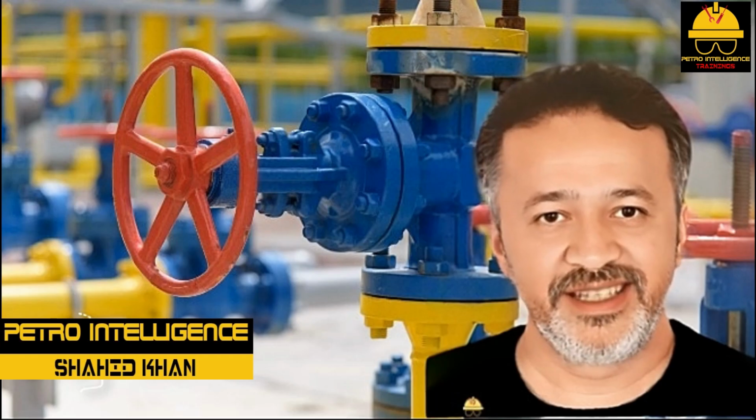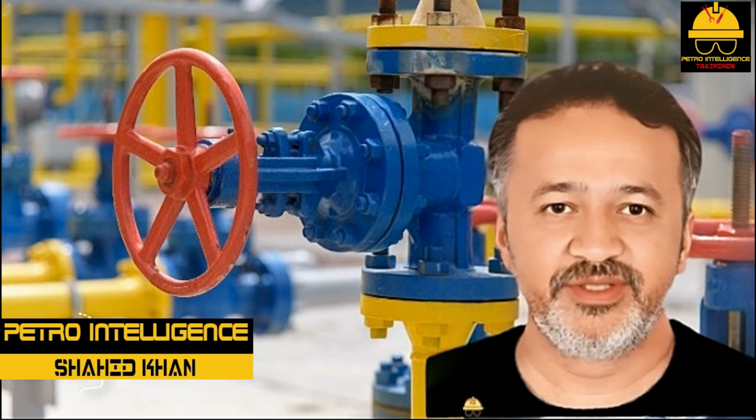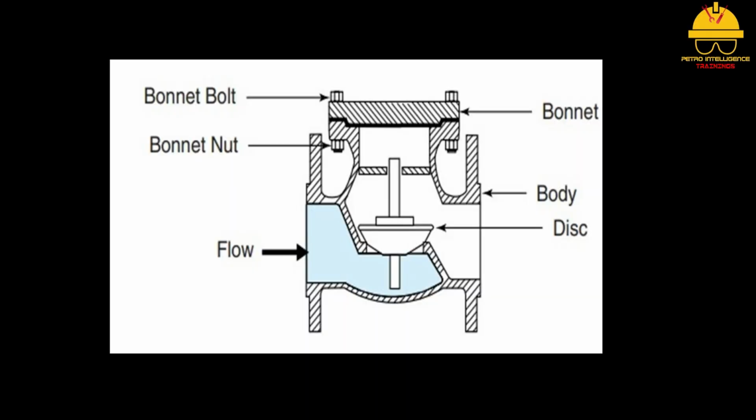Another design is the lift check, which has a disc that rests on the seat when flow is idle and lifts when flow is active as shown in picture. Special guides keep the disc in place. Like the swing check, it is designed to close when flow reverses. Lift checks are ideal for systems in which flow rates fluctuate. The lift check is more durable than the swing check.